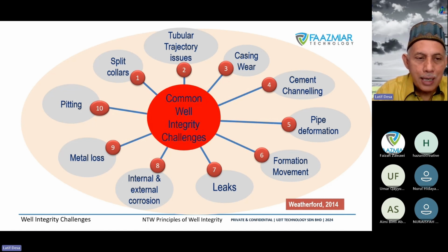I think we have covered that. And metal loss, the thickness loss, pitting. Pitting is actually the common surface issue with corrosion. When you have a marine environment, salt, oxygen and water, the corrosion starts to be almost exaggerated, and it is going to be eating up the wall thickness from outside. So pitting, after some time, can cause a total failure of the casing. We have seen the surface casing and the conductor casing become very badly corroded and fail to provide the structural support to the well.